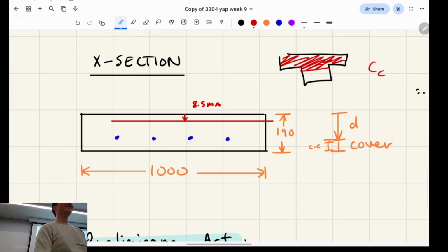But like this part is a function of dn, and these ones are set if your neutral axis goes into the web, basically. And if we add reinforcement and push it back into the flange, can you do that? Yeah, that's actually one reason. I think there's a workshop question on that. They add compressive reinforcement so that it stays in the flange. Yeah, it is a good idea.